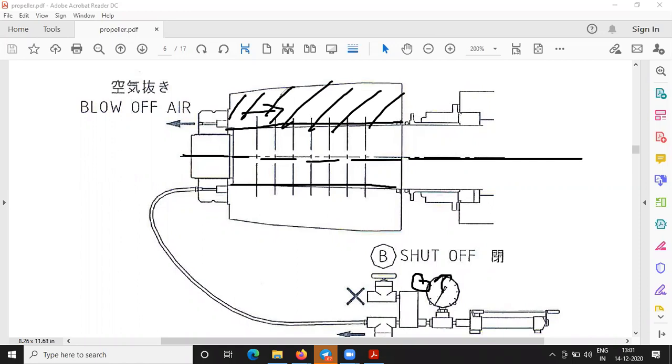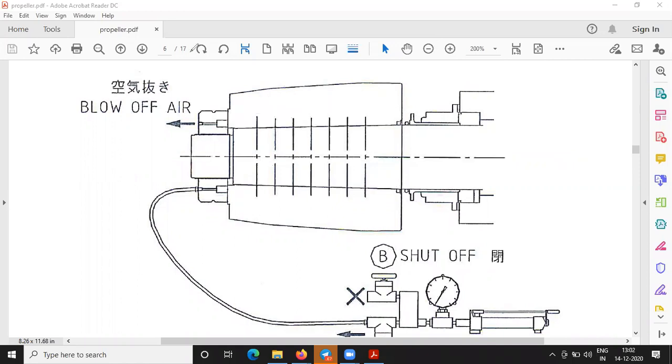And now there is no further movement of the propeller boss possible onto the shaft. Now what will happen? Now you will start seeing that there is a slight increase in the oil pressure here. That is the point you can start knowing that there is a building up of friction starting in between the propeller shaft as well as the boss. Understood? Yes, sir. Sir, you mean the pressure whatever we are giving, it is going and aligning the hub and the shaft. Then after the pressure will start to develop. Yes, sir. Because until now, you will not see any pressure here.